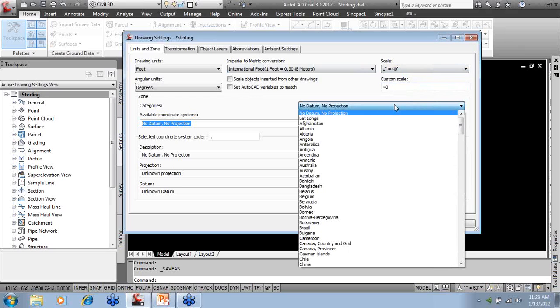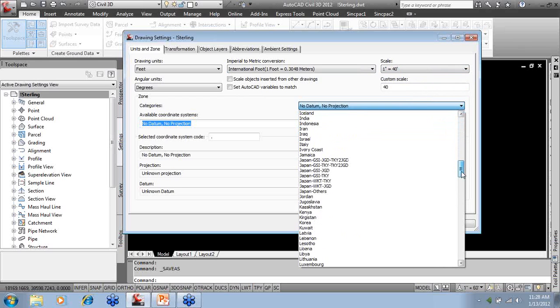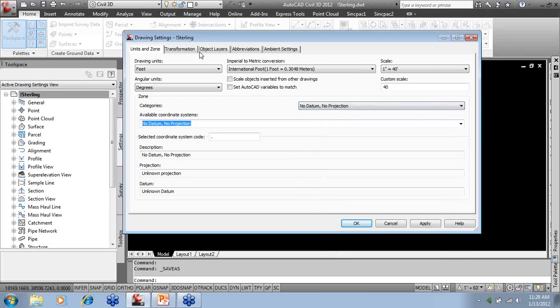We have the option to go in here and set the categories for the list. If we're using GPS, latitude, longitude, we can tell where the coordinates came from. If you notice there's USA, Arizona, you can set this at any time. If you're not doing latitude, longitude, you don't have to worry about it. Talk to your surveyor about this for more information. You can also use this if you want to pick a great vacation spot anywhere in the world. They have just about everything in there.